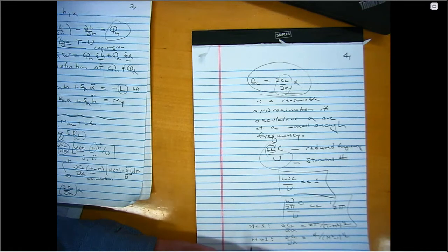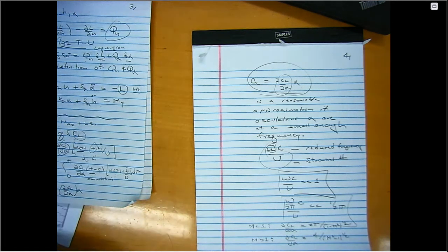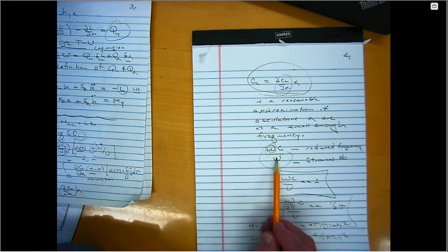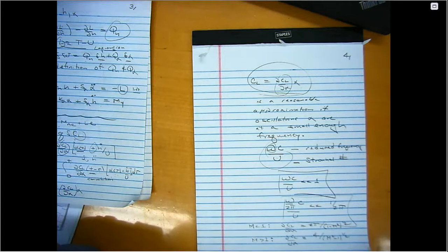On the other hand, both of these formulas tell us that something really bad is happening when the Mach number goes to 1. Both of these formulas blow up. They really tell us that dCL/d alpha, the number, becomes really large, which it does, but it doesn't go to infinity. But linear theory, classical linear theory, which assumes that omega c over U is really small compared to 1, tells us that things blow up.